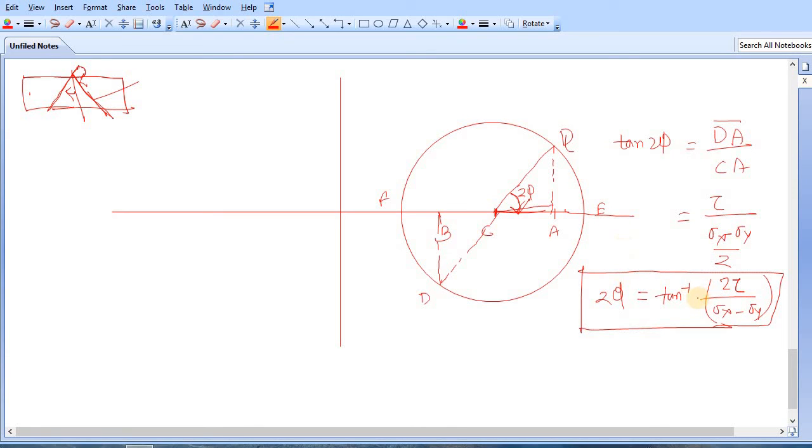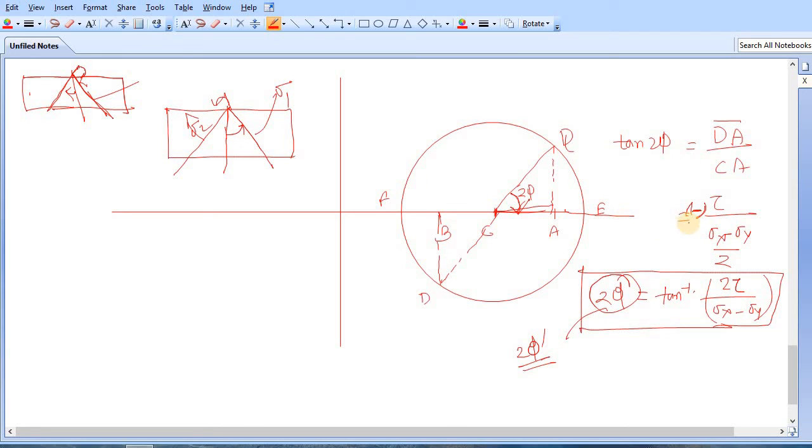Now here is a problem related to sign. In some books you can see in this formula there is a negative sign. Don't be confused with that sign. Simply when you take the negative sign, you will get a phi value, let's say 2 phi dashed, and in that case you have to rotate your actual plane in an anti-clockwise manner. So here this is your sigma 1, and again for pi by 2 anti-clockwise, this is your sigma 2. Clear? So don't be confused with the minus sign. When you take clockwise measurement, you simply rotate it clockwise. If you take anti-clockwise measurement, you have to put a minus sign, and in real case you have to rotate your plane in anti-clockwise manner. That's all.